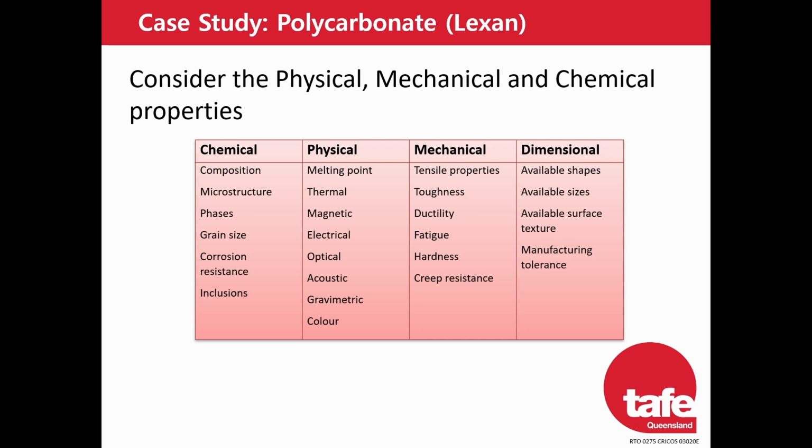Next, I'll move to mechanical properties. So polycarbonate has exceptional impact resistance. Polycarbonate is virtually unbreakable and can withstand flying chips or tool breakages, providing excellent operator protection. It has high toughness, resists cracking or shattering under sudden loads or shocks, and it has good dimensional stability. It maintains its shape under mechanical stresses, ensuring it stays securely in place over time.